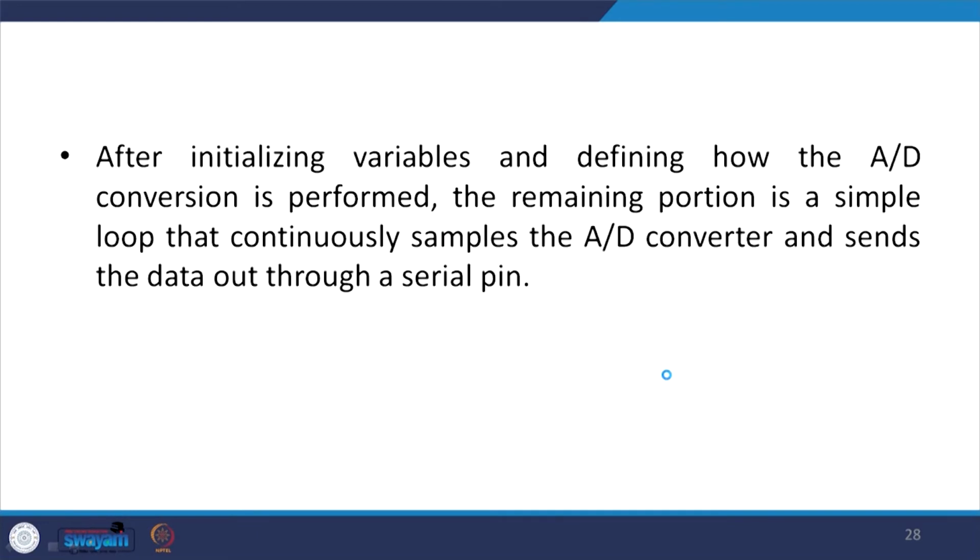And after initializing variables and defining how the analog to digital conversion is performed, the remaining portion is a simple loop that continuously samples the analog to digital converter and sends the data out through the serial pin.